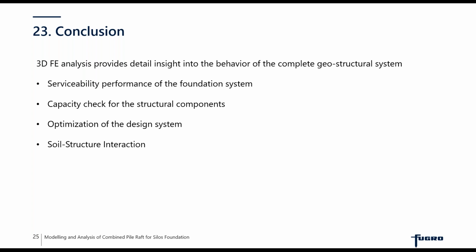As in one of the slides I showed, it's the behavior of the structure which governs the settlement criteria and the amount of forces generated in various structural components of the superstructure. That can also be modeled simultaneously with the construction stages which need to be considered, and this provides a better insight into the performance of the superstructure foundation system.